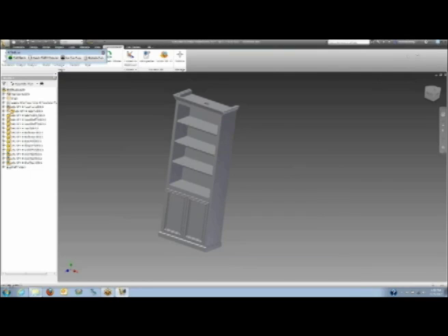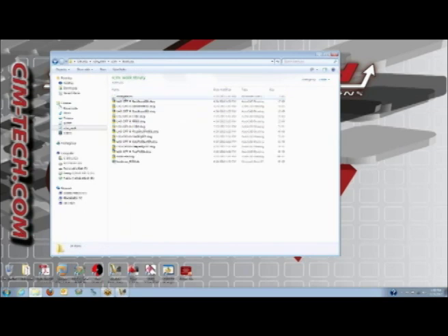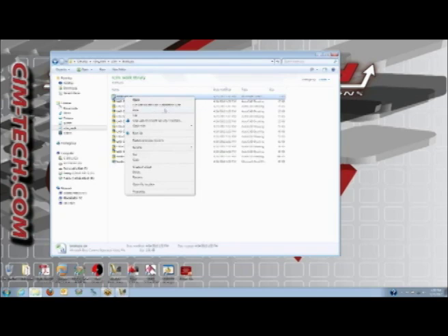I now have programs for each of my individual parts in that assembly. Here's the folder with today's date and time. There's all the individual parts using the part names from Inventor. And I have a CSV file which has my name, material, and quantity. And we can go with one more right click, cut with AutoCAD.